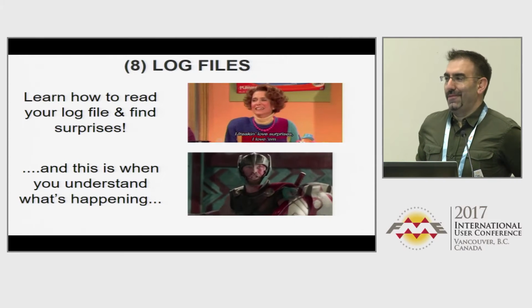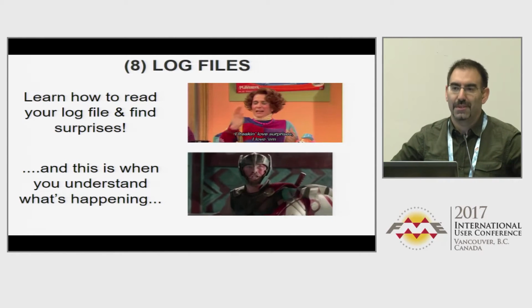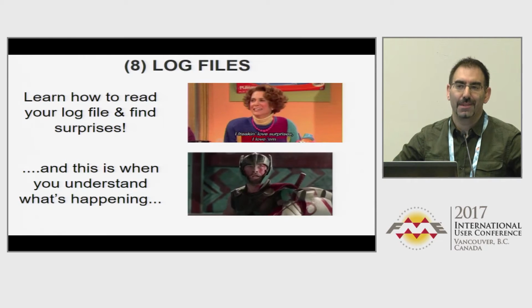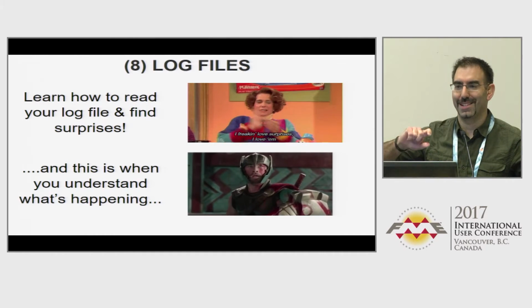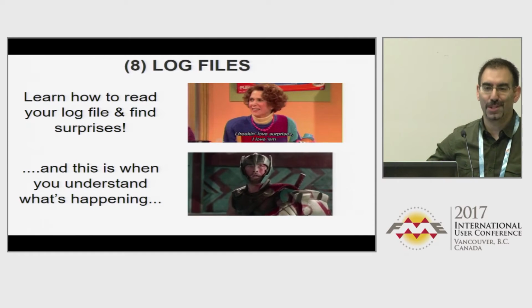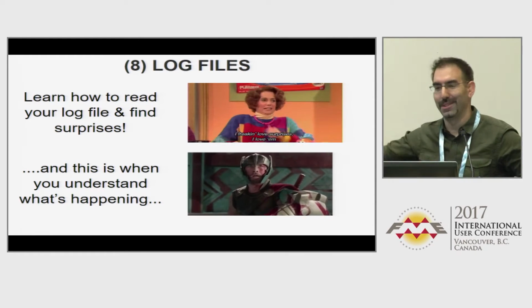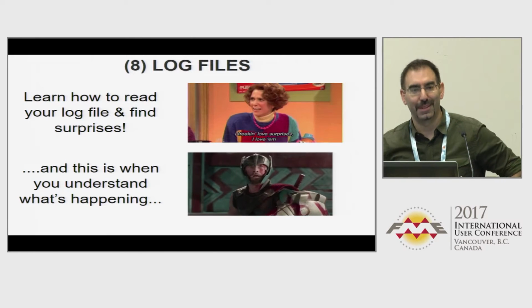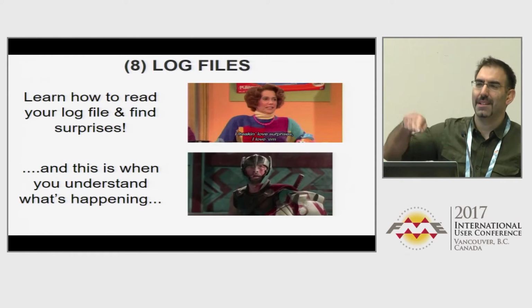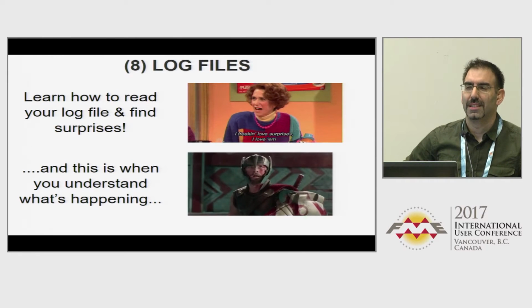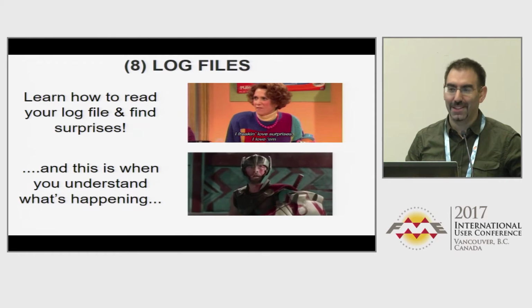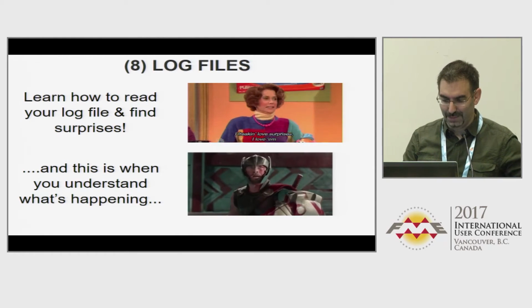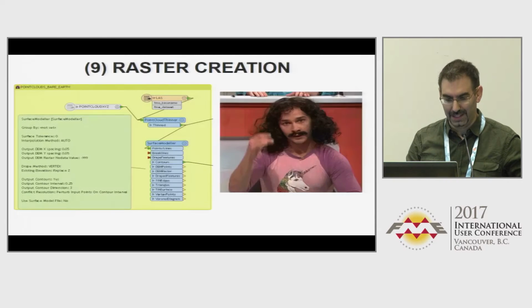Some of the time I've seen surprises where I go to write stuff out to SDE and I think it's written out, and I'm not paying attention to the log file, and there are little red error messages or little blue messages that tell you what features didn't get written. At first you're kind of like, okay, I just need to get through this job, just write it. And then later on you're looking at your output two days later and people are like, well, what's that on the map that doesn't look right? I was like, oh yeah, I missed a donut. So have a look at that. There's plenty of stuff in there. It's just good practice to have a look at it.